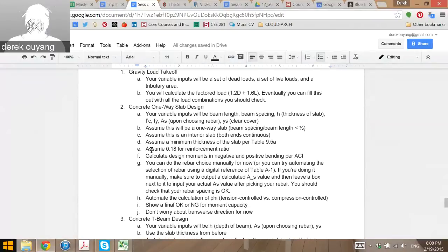The secondary beam you've placed, which you've decided how many. It's either 1 or 2 or 3, and that's probably your only options. And you want to obviously be conservative. So make the span as much as it can be without collapsing. Right? Then you're designing this, which is a T-beam. Because you've just designed the slab, which you're going to decide what the effective length is. There are like 3 checks you have to make on when you find the minimum. You can certainly make that automatic, right?